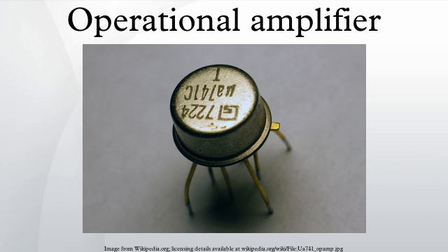Differential amplifier. The biasing circuit of this stage is set by a feedback loop that forces the collector currents of Q10 and Q9 to match. The small difference in these currents provides the drive for the common base of Q3/Q4. The summed quiescent currents of Q1/Q3 plus Q2/Q4 is mirrored from Q8 into Q9, where it is summed with a collector current in Q10, the result being applied to the bases of Q3/Q4. The quiescent currents of Q1/Q3, I1, will thus be half of I10, of order of approximately 10 µA. Input bias current for the base of Q1 will amount to I1 divided by beta, typically approximately 50 nanoamperes, implying a current gain HFE of approximately 200 for Q1, Q2.